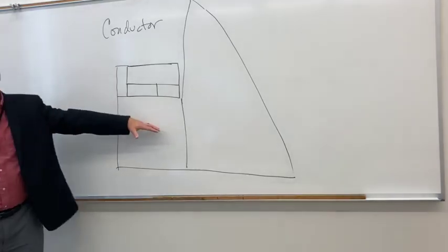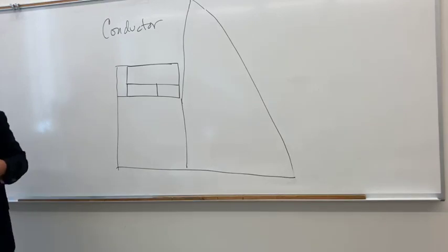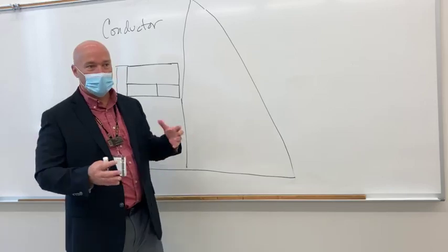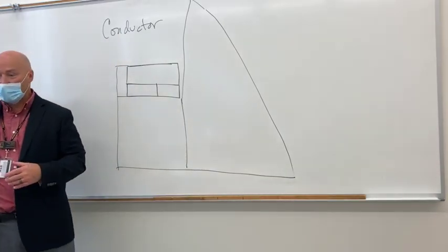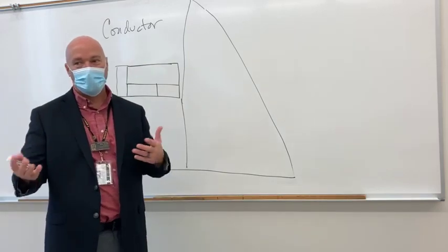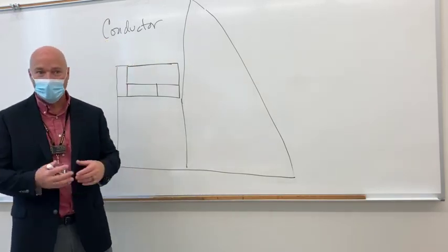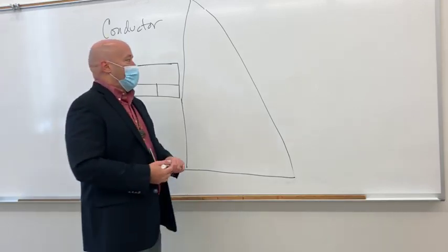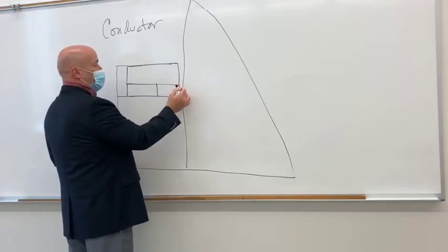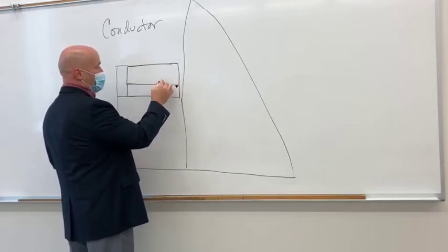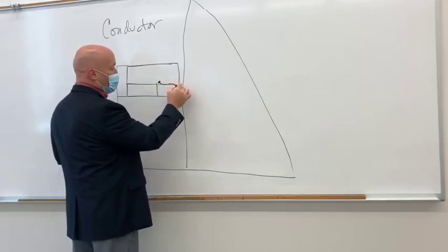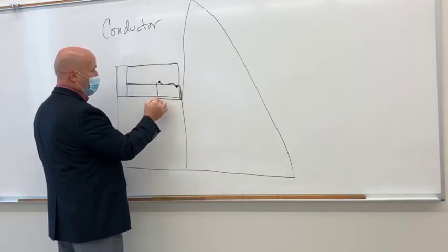I don't wanna put up another fence, so I put up an electric fence. If you've never dealt with an electric fence, it's basically a generator of high voltage and low amperage. You get about 1,500 to 2,500 volts coming out of an electric fence generator. So what I did was, at the edge of the garage here, I plugged the electric fence generator in inside the garage, brought it around, and ran a wire all the way down to here, okay?